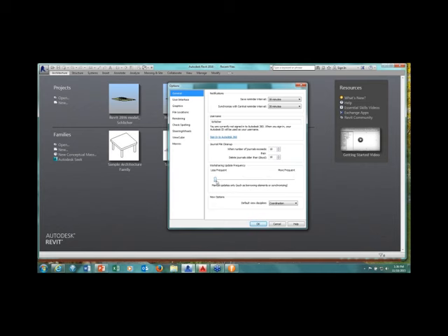So if everybody is not adhering to this standard here, I saw an example actually. I had 2 users in a remote office once. One of them had the setting set this way. The other one had the setting all the way to the right. They called me one day. They were sitting right next to each other in the same office. One of them was doing a sync to central in about 30 seconds. The other one was taking 4 minutes, and we couldn't figure out why. This was why. Once the user moved this setting to the left, then he also got 30-second sync to central times.